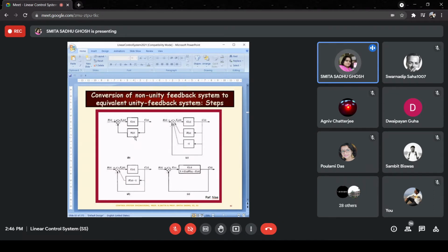Here, they've gone by the method of block diagram reduction, unlike the one that you usually apply. That is, you take the closed loop transfer function and see how it is going to become equivalent to some G equivalent. So you take both the closed loop transfer functions, compare, and then you get it directly, algebraically. That is fine. That's one method which is going to give you a correct result. But they have done an alternative method over here, put on this slide for your knowledge or benefit.